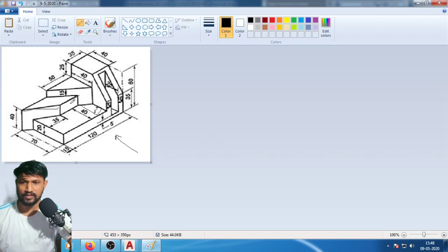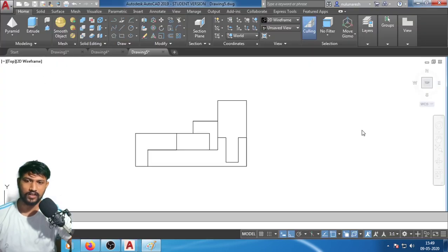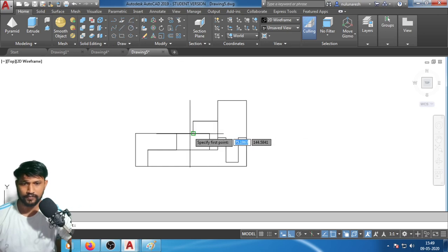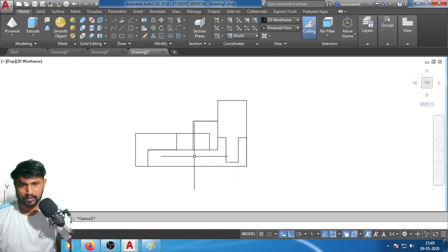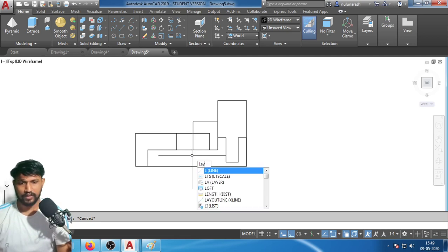But whereas this edge here, okay, this particular edge will go down up to certain dimension, but we won't be able to see that dimension, so I'm gonna mark this one with a dotted line. Up to this one, I'm gonna have to create a new layer.